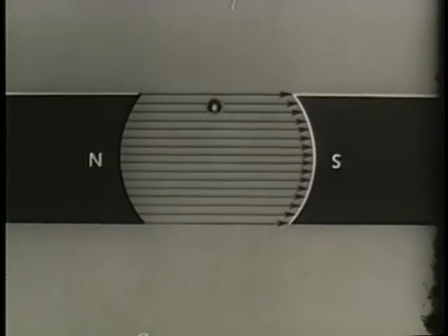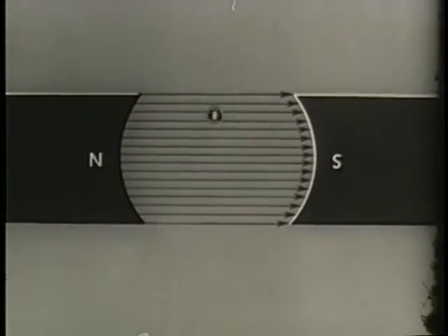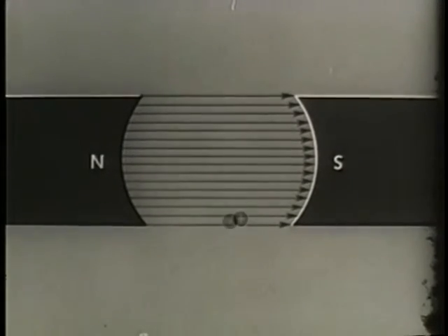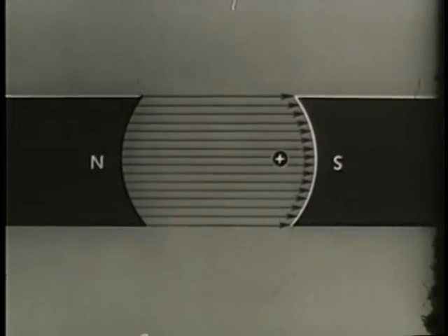But the conductor in an actual machine is not moving in a straight line, but rotating. When the conductor moves in a rotary path, the number of lines cut varies depending on the position of the conductor. At the top of the field, for instance, no lines are being cut and no EMF is generated. As the conductor keeps turning, the number of lines cut increases, so that at a quarter turn, or 90 degrees, the maximum number is being cut and maximum EMF is generated.